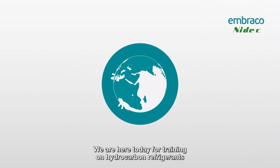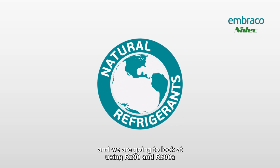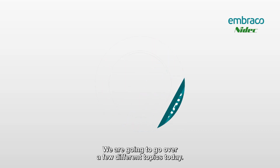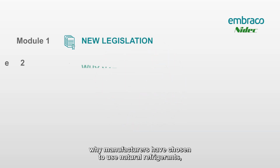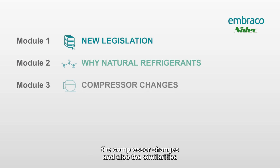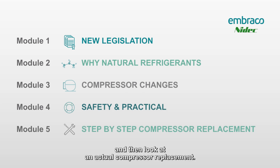We are here today for training on hydrocarbon refrigerants, and we're going to look at using R290 and R600A in light commercial refrigeration equipment. We're going to go over a few different topics today. We're going to look at legislation, why manufacturers have chosen to use natural refrigerants, the compressor changes, and then also the similarities between these compressors and the systems, how to stay safe when working on these systems, and then look at an actual compressor replacement.